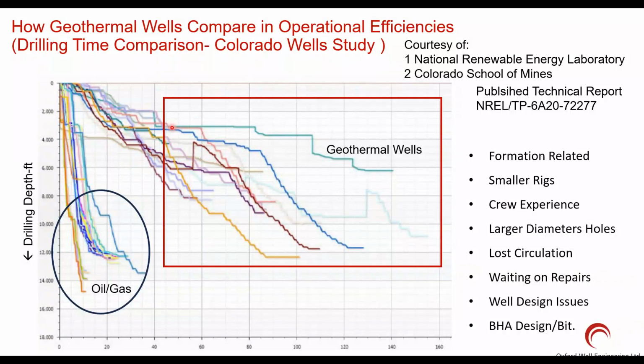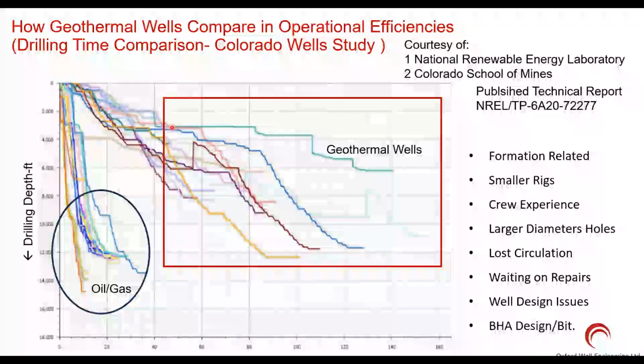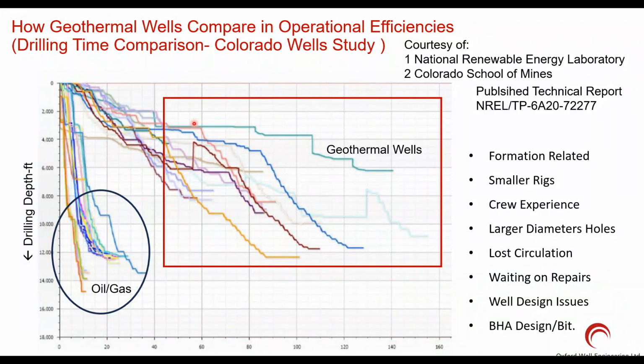Digital technologies can automatically detect and put it on the table, all these small bits and pieces of flat time. When you combine the small flat time together, sometimes it comes as high as 10% of the drilling time or the rig time that the rig had been doing this project. The whole well time, 10% of it is unknown invisible time. You can catch it in the real time.